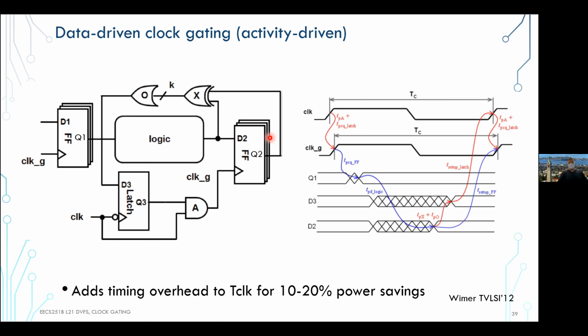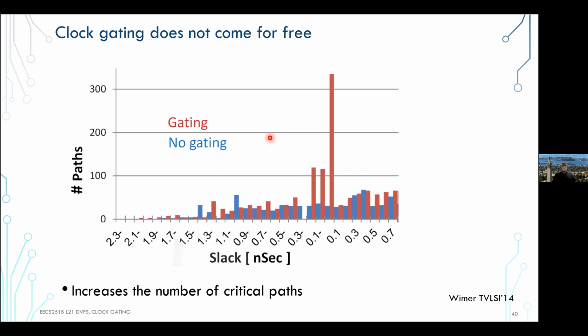So, premature optimization, there's a saying, is the source of all evil. And of course, the potential penalty, as we said, of doing what I've just shown is that you significantly increase the number of critical paths with a negative slack because you're adding that extra delay in a bunch of places.